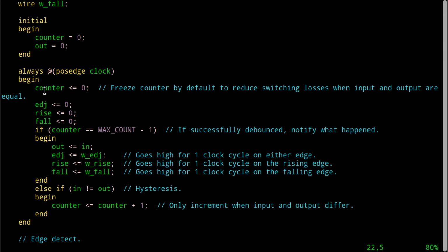Now you might say I just set it to 0, but not, because remember how this works. The non-blocking assignment will not update the counter register until after this always block is fully completed. So asking about its current value here gives you the value before this will have completed. Okay? Again, another reason we want to look at somebody else's code so we can understand these things.